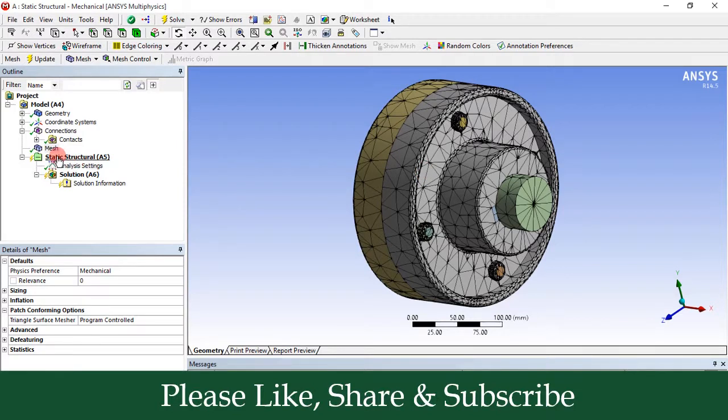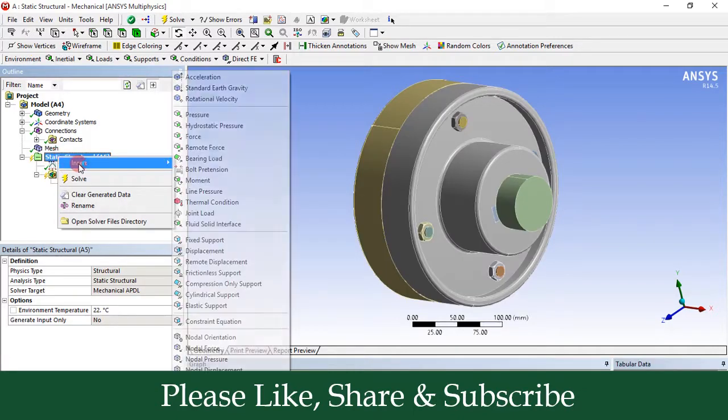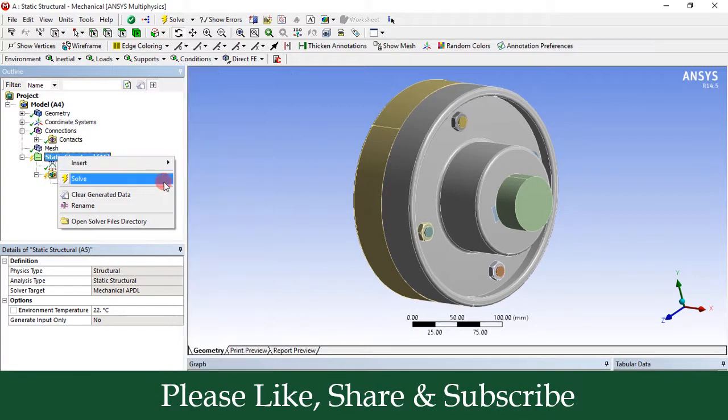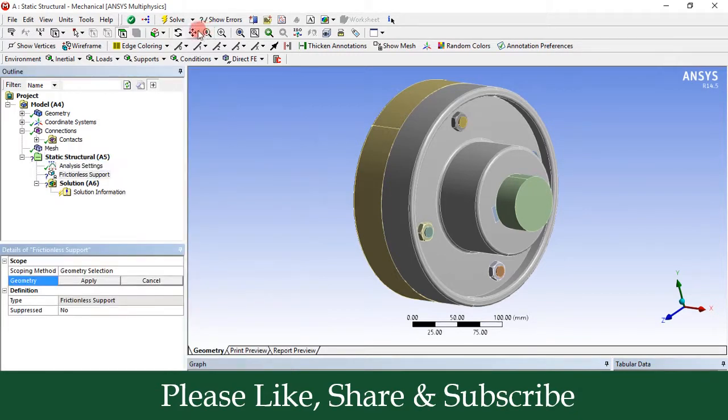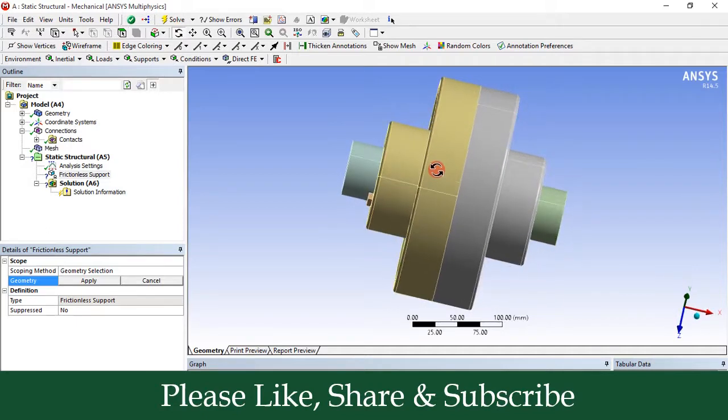Okay, so now right click on static structural. By using this option we are going to apply the boundary conditions. Now right click on static structural, go to the insert, go to the frictionless support, and now we have to apply this frictionless support on the input shaft as well as output shaft. So for that purpose we have to select the geometry.